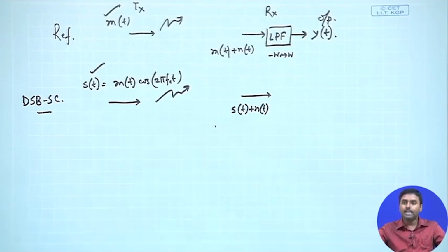First thing we will do is, this is modulated, so the frequency will be centered around omega c or f_c. I have to employ a band pass filter, because we have already told that whenever it is modulated, I want to take just my signal which is centered around omega c with a band of 2W. I also want to take just the minimum amount of noise. Therefore, I will put a band pass filter, so that just the minimum amount of noise which is centered around f_c and 2W bandwidth will be taken into account.